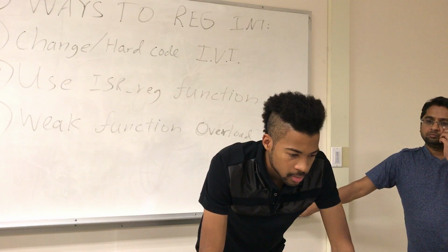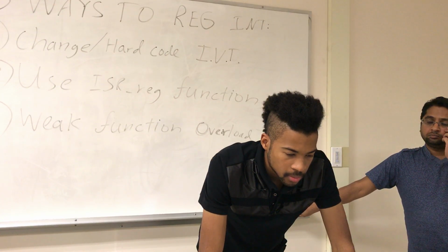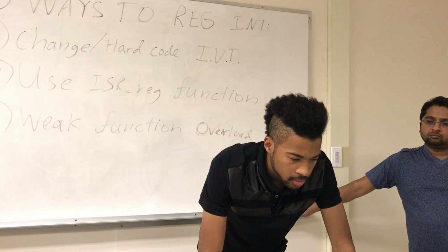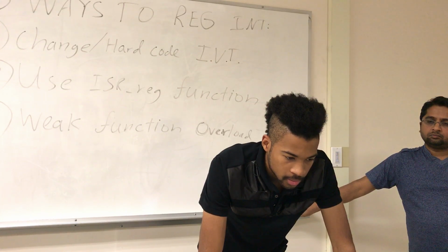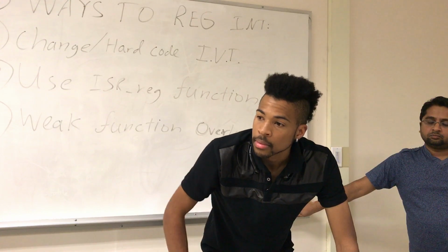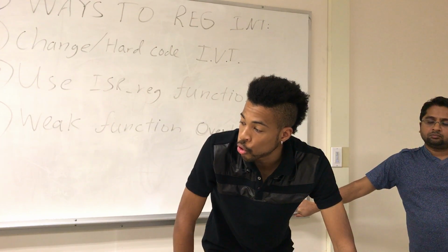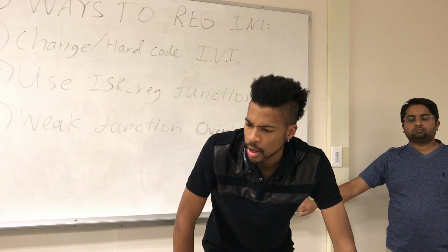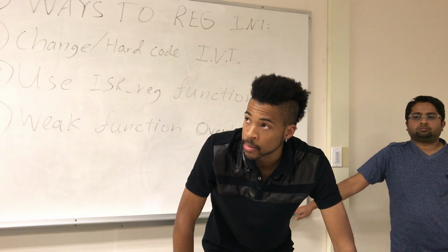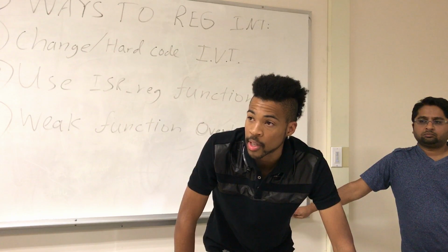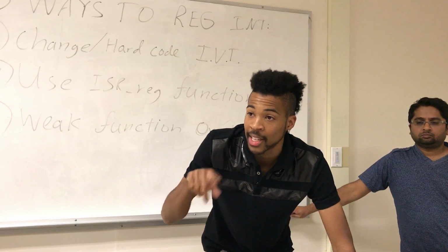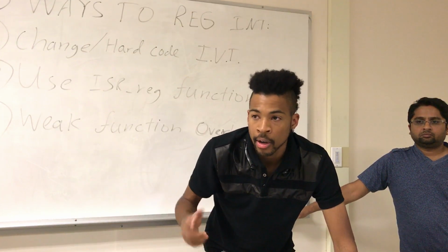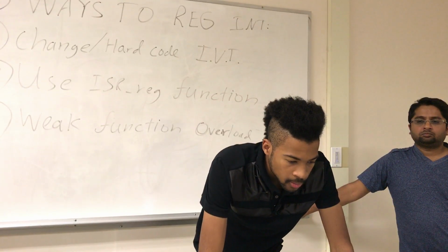Okay, so even if you have a pin set up for, say, SPI, does that mean you can also have an interrupt come in on that pin while it's being used? Technically, you could set up a GPIO interrupt on a pin that's being used for something else. I've seen examples where someone had a PWM, and every time the PWM had a rising edge when it restarted its cycle, it did something else. So even though it's an output, you could still trigger off your own internal signals. Okay, so that is a possibility.